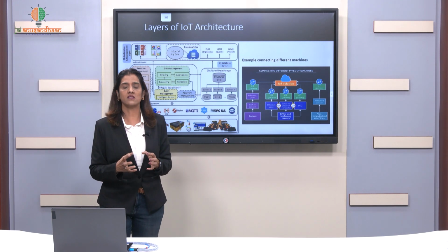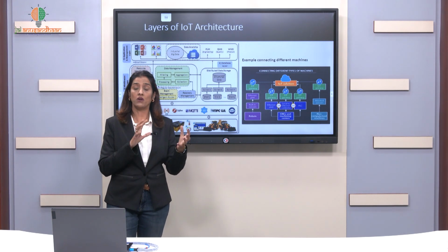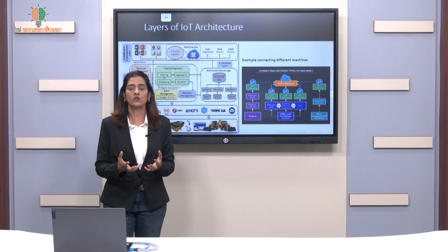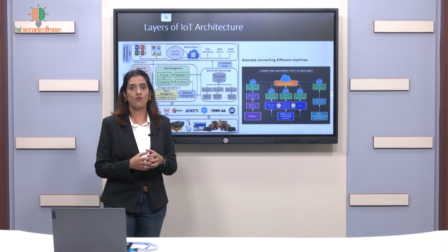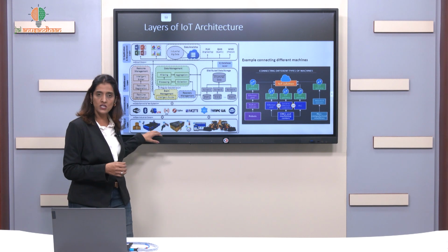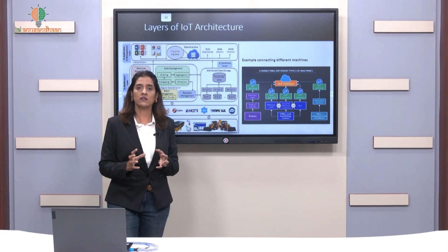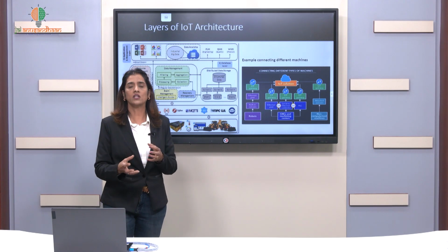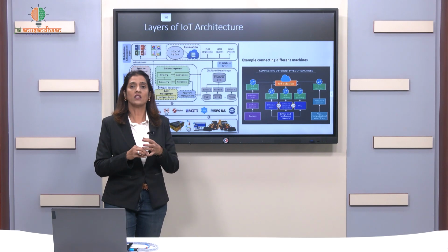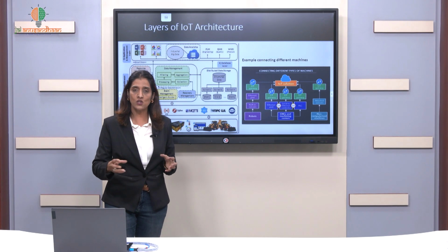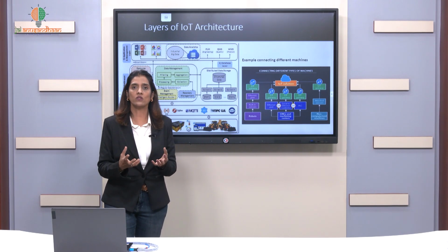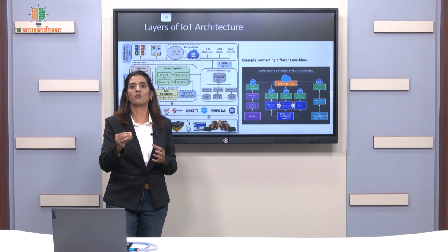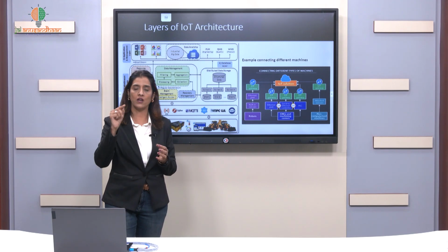Massaging the data is a big field of data analysis, out of which you conclude something about that data. For example, if one of the machines is not doing well, say its temperature is beyond some range, then you sense that temperature, collect the readings, and conclude that yes, this machine is going to die, or this machine will not be performing after 2 days if this is the trend of the temperature.